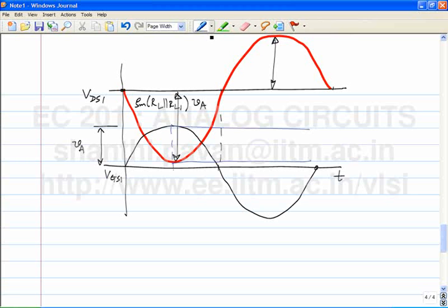So what did we conclude that day? We concluded that the transistor will be just at the edge of saturation provided the drain is one threshold below the gate. The black waveform is the gate waveform, the red waveform is the drain waveform. And the drain clearly is going below the gate at this time.